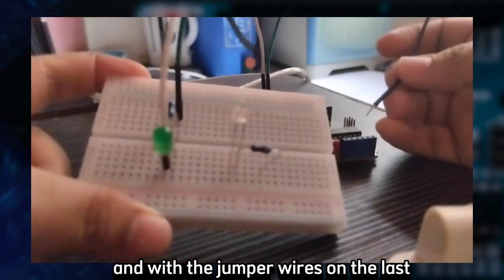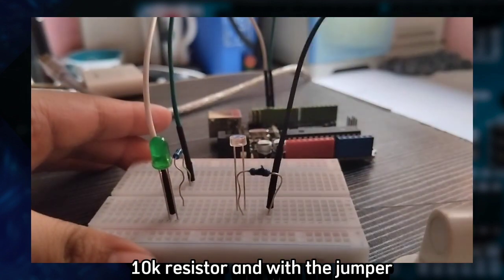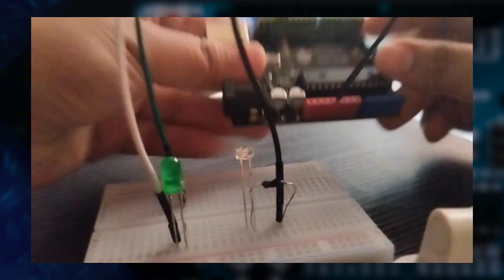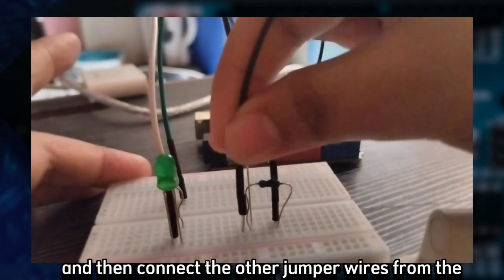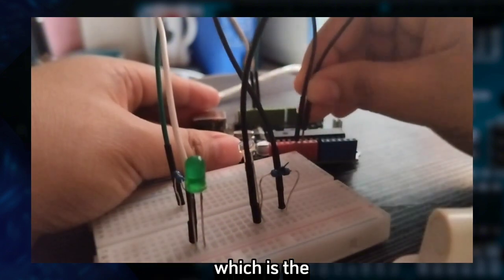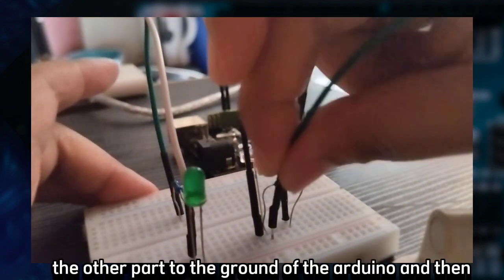Put a jumper wire on the last of the 10K resistor, and connect the other jumper wire from pin B. Then connect another jumper wire from the lowest part, or the minus, of the ambient light sensor, which is the right side of the 10K resistor,